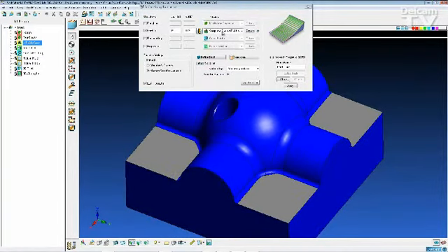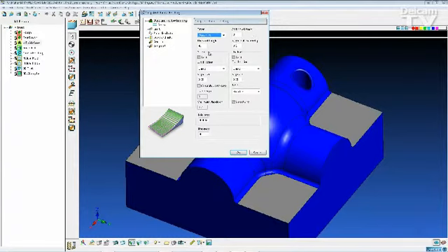We also have a steep and shallow. So here I've got some certain surfaces selected that I want to finish machine, and we can machine the steep regions with the Constant Z strategy, and the shallow regions with either a raster or 3D offset. I've also turned on the spiral options, and we have a threshold angle to decide where to start and stop the steep and shallow settings.